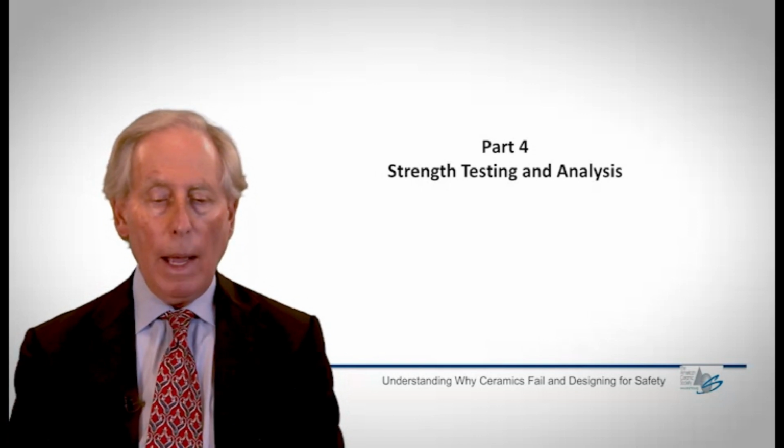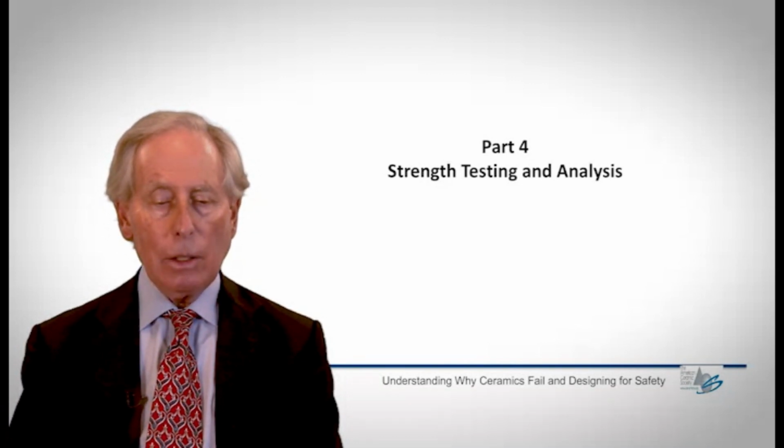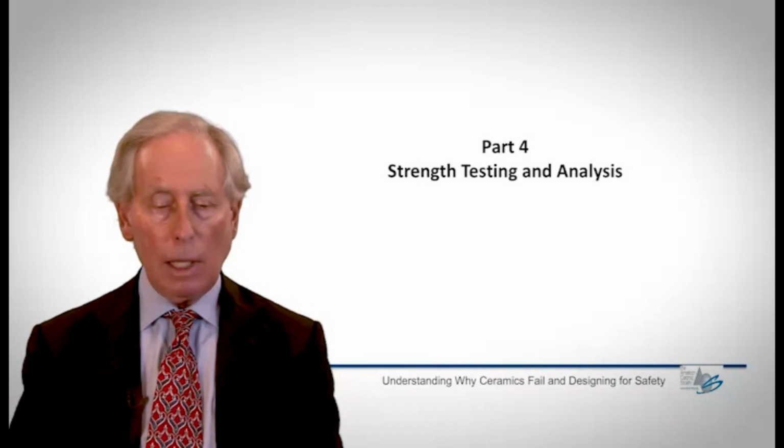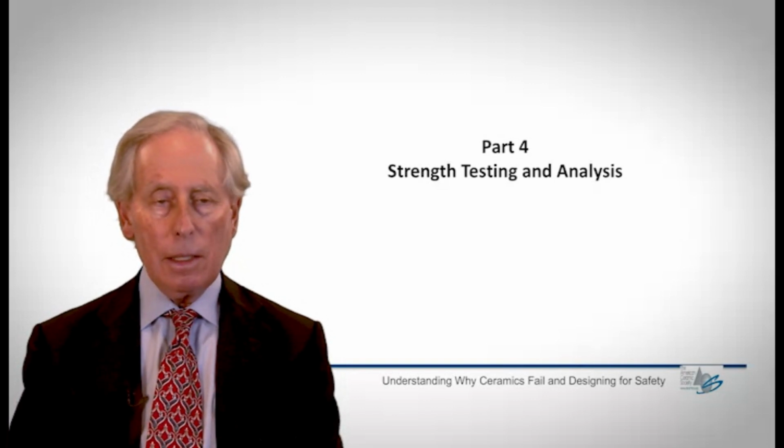And by way of outline of what I want to talk about here, first of all, I will only talk about ambient temperature fracture. Elevated temperature fracture certainly does occur in those applications, but I'm not going to cover that in this lecture. I'm going to talk some about uniaxial flexure tests, biaxial flexure tests, and also a very little bit I'll show you direct tension tests. One slide or two slides on fiber testing, and then a fair amount of time spent on statistical analysis.